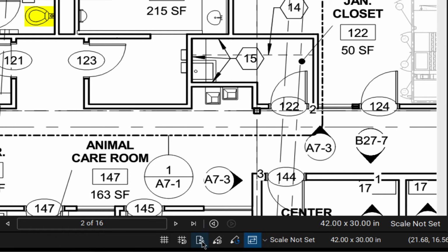Now, why the heck would I want to snap to a content? Well, if I turn on snap to content and draw a line, I can draw a line from that end to that end. I can have a nice line from endpoint to endpoint, and I can use Review as a drawing tool. With it selected there, I'm going to hit the delete key on the keyboard to get rid of it. I can hit escape to get out of whatever is selected as well. So that content snap is pretty nifty.